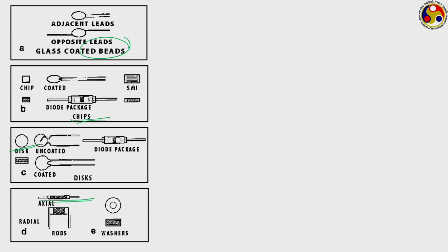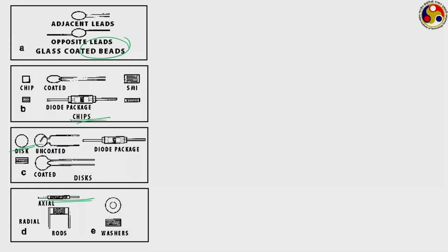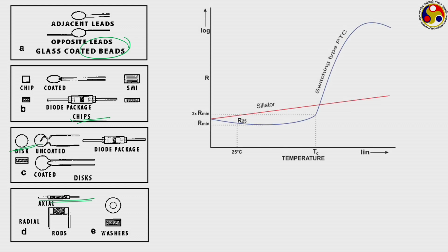And finally, before I close the thermistor part, commonly we talk about materials having negative temperature coefficient, but actually there can also be thermistors which have positive temperature coefficient. Certain semiconductor material which involves barium titanate can have quite high positive temperature coefficient, just like shown here. Sometimes heavily doped silicon can also act like this.